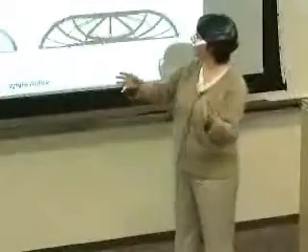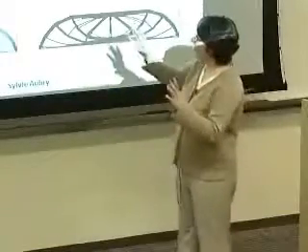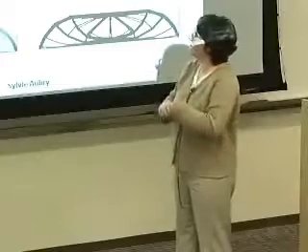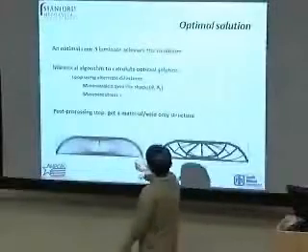So the way it works is the following. You have a minimum over the shape. Now the shape is given by the proportion theta and the laminate, A_L, which is a function of theta, that you know analytically as a function of theta. And so you start with the initial shape. Then you minimize the stress given the external loading condition. And then you iterate like that until your algorithm converges. And once it converges, you get this kind of shape.